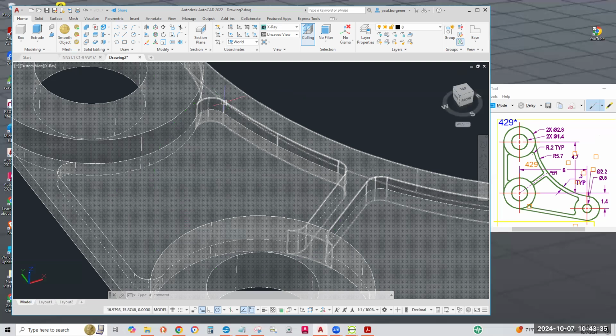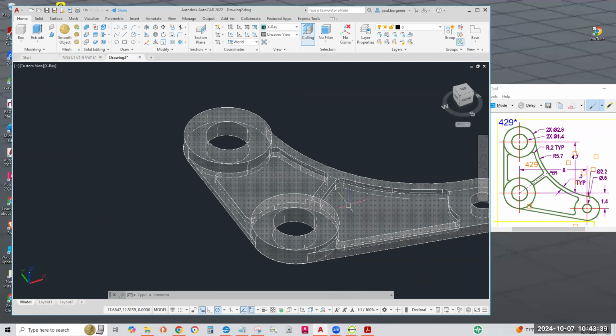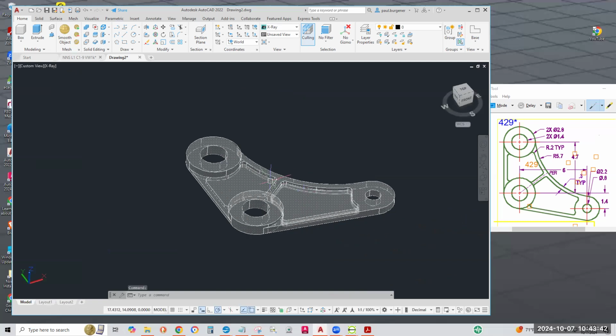How about we move the 0.2 and the 0.4 stuff up a 0.1 unit. And then we'll move the webs up 0.1 unit. With O snaps, you don't have to do the arithmetic, but since we use 0.2, 0.4, 0.6 extrusion heights, let's take advantage of the easy math.